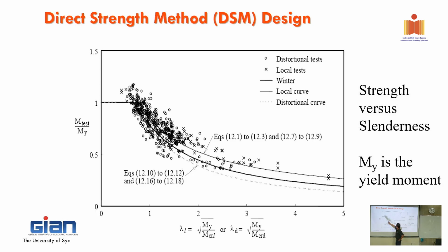But just talking about this one, because of the interaction. Sometimes in some tests, if you don't have the restraint, it might fail in a little bit of local buckling and a little bit of distortional buckling, and that drops a little bit down to the pure curve. But not all of them, right? It's random that you have some sections that have some interaction.